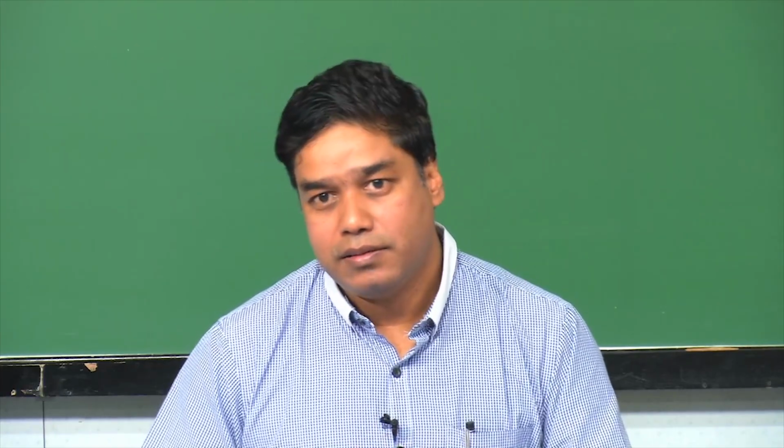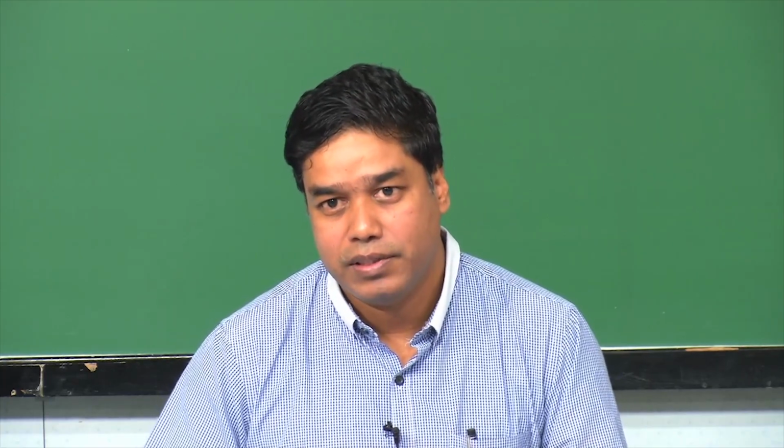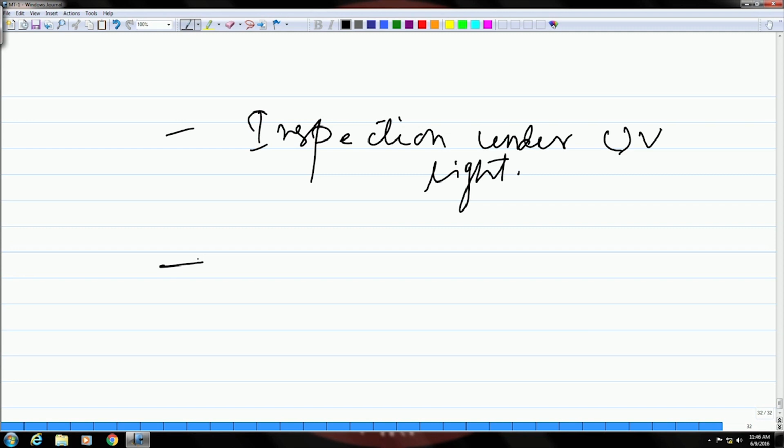If it is still magnetized, the magnetic field of that component can affect its function when it is used along with some other parts in a particular system. So, the last step in this case should be to demagnetize the part before you wind it up.